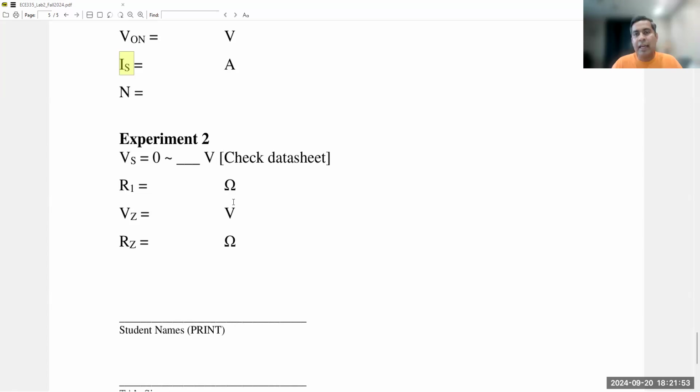when you are sweeping the voltage supply for these diodes. One of you can measure the forward bias direction, one of you can do the Zener diode forward bias direction, and one of you can do the Zener breakdown, the reverse bias condition. You can divide the work and get experience of measurement and actually running the experiment. That is a very valuable experience that will give you a better understanding of these diodes' characteristics and how they behave in a circuit environment.